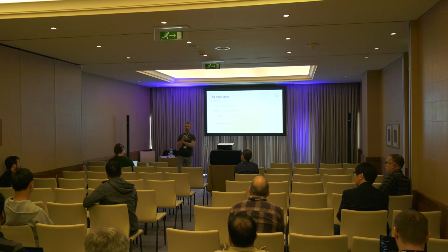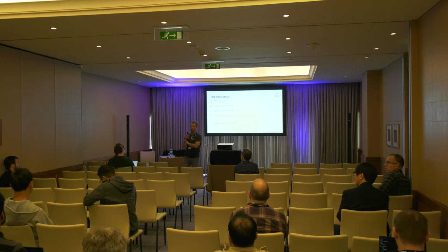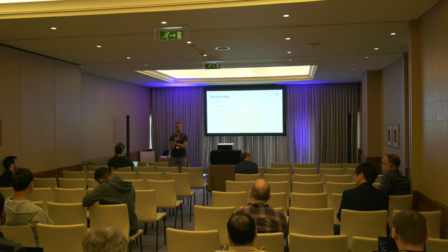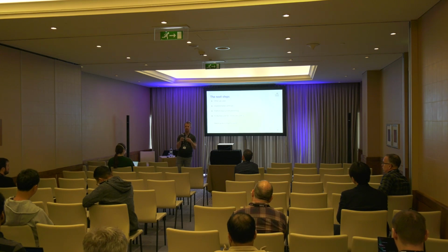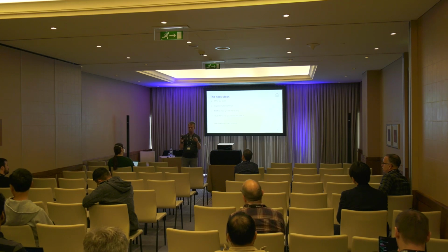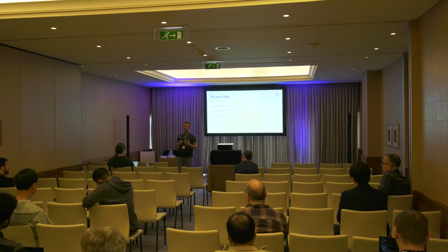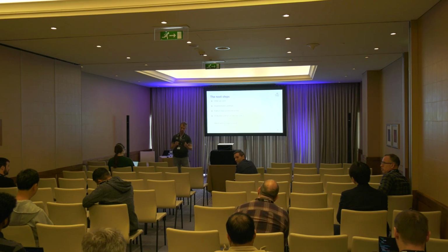Well, part of that is already supported today. We might need to extend the decision making about the states a little bit, because today, if there is a wake-up configuration required for some of this in the topology, you simply don't turn things off. You just leave it in the shallowest state possible. So what you're saying is maybe that is not good enough, or you might want to allow some states even though you have a wake-up.